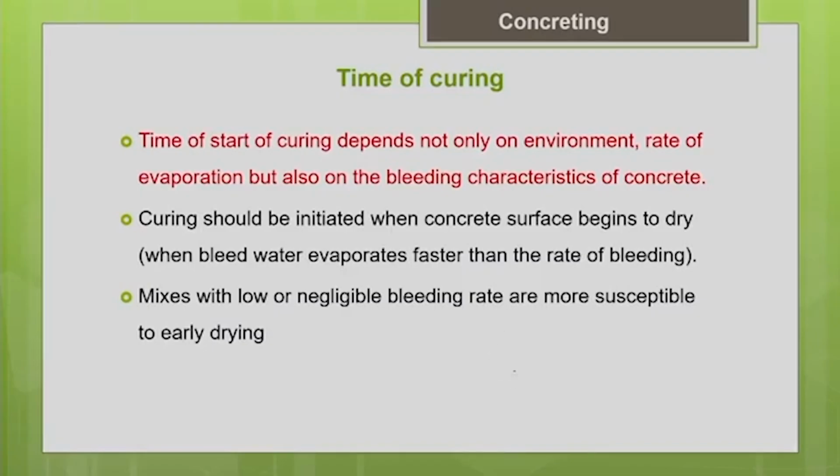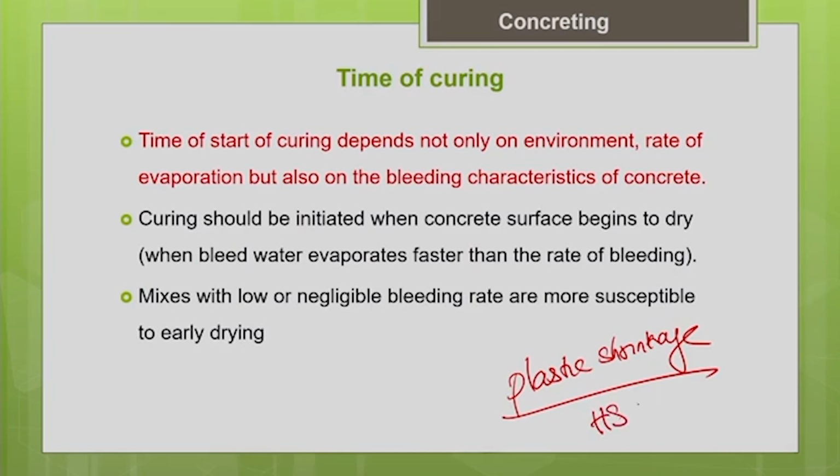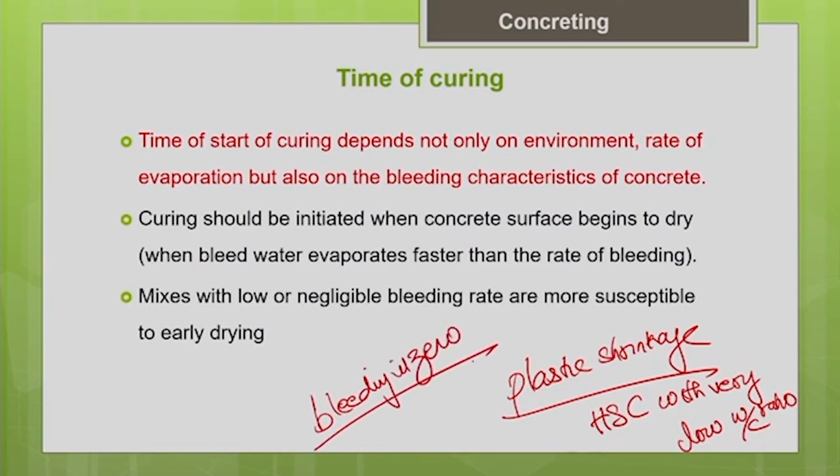Otherwise, what happens is your drying will result in shrinkage cracks. They call them plastic shrinkage cracks, the shrinkage which occurs in the fresh state of the concrete. Particularly it happens for the high strength concrete mixes with very low water to cement ratio, where bleeding is zero or negligible.